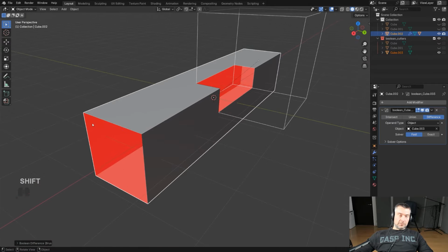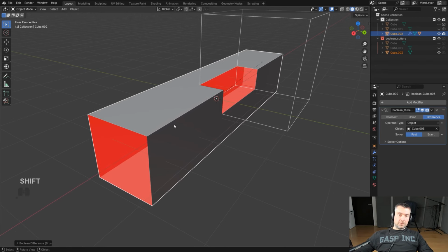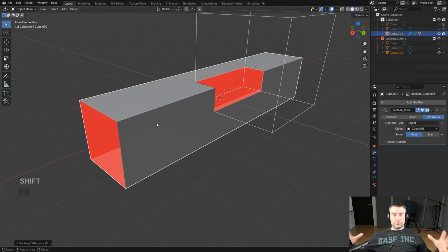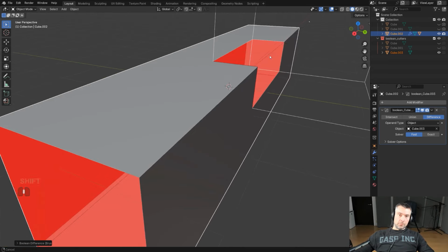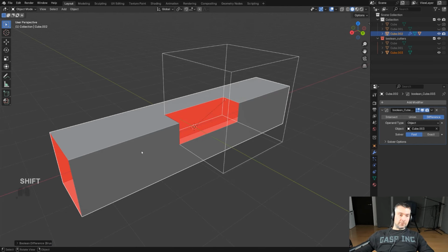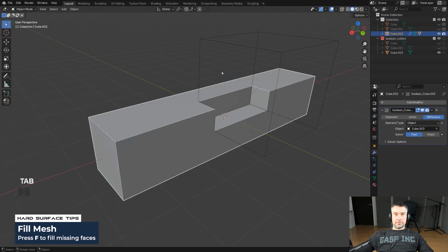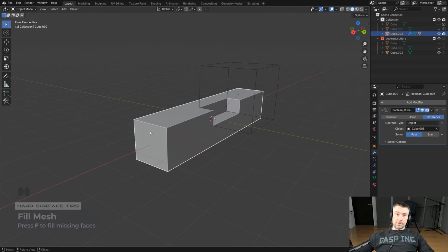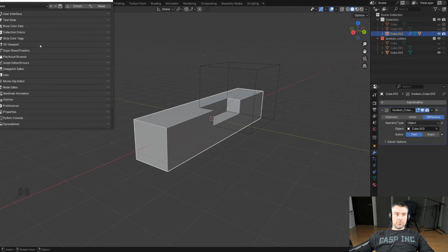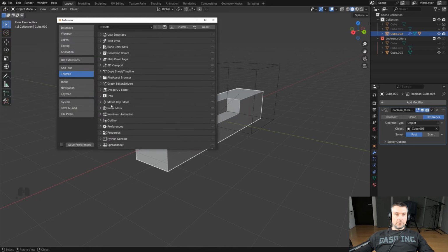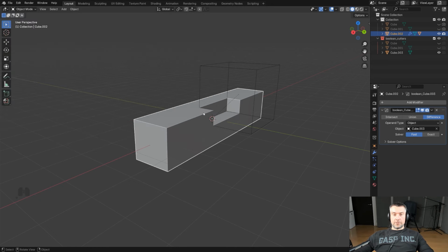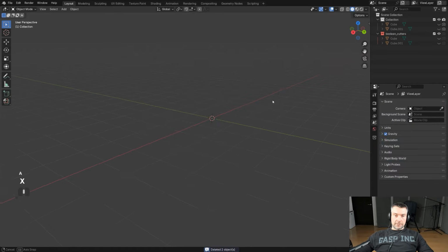Well, because your mesh is not manifold, and you need to boolean a closed, watertight, manifold mesh in order to have these faces appear. So if I close this mesh, right, boom, these faces appear. The easiest way to find the missing face is to turn on this face orientation thing and switch this alpha, like I showed you here, under 3D viewport to 0, so you can only see the red mesh, right? So that would be about booleans.